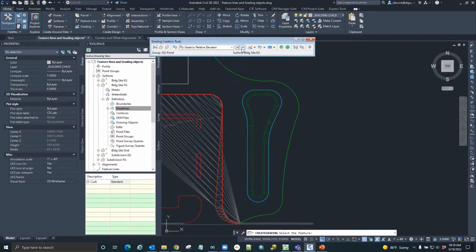They've been around since the inception of Civil 3D in 2005, but they are as fickle as they come when it comes to tools. You can't just delete one of these and think there's nothing wrong. There's a specific way you have to delete these, and a specific way they have to interact with each other. As soon as you go outside of those parameters, you end up with what I call gremlins in your drawing, or something that has to be fixed. Yeah, you mentioned gremlins. I refer to it as drawing bloat. As you delete those, you always have to audit and purge these things out, because they leave some junk behind.